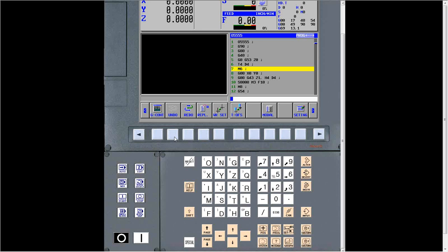I'm going to combine two of these because they both have to do with what you're able to do with Manual Guide I on a lathe with live tooling and a C-axis. And one of them is, are you able to thread mill on that kind of machine? Yes, there is an option for a live tool lathe, just like on the mill, that you can do thread milling on the OD also. Yes, as long as you've got the right axes on a live tool machine. Okay. Yes, it is possible.